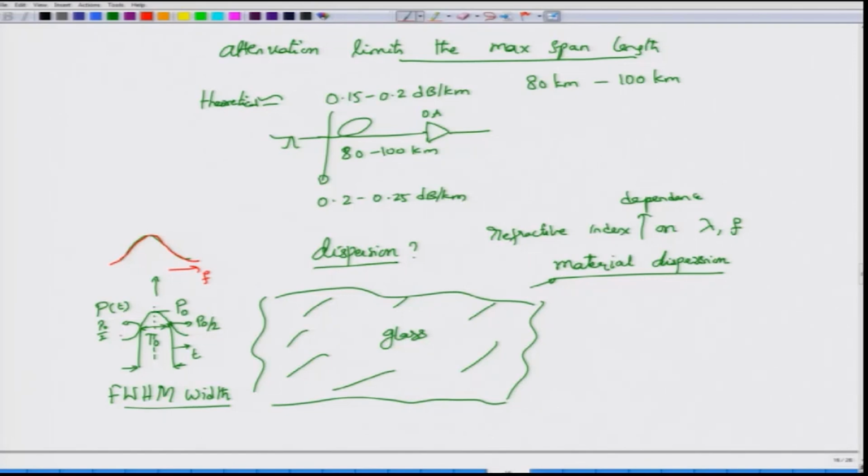So, when I am given the time domain pulse, I take the Fourier transform, and once I have taken the Fourier transform, I have gone from the time domain to the frequency domain. And in the frequency domain, what we really are saying is that there are all these different frequency components. Of course, there are an infinite number of frequency components because this is a continuous time signal and the corresponding Fourier transform is also continuous.